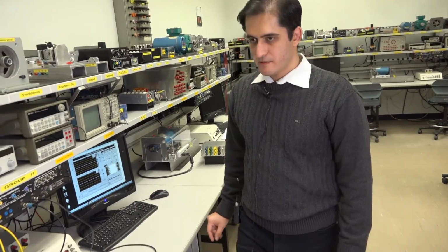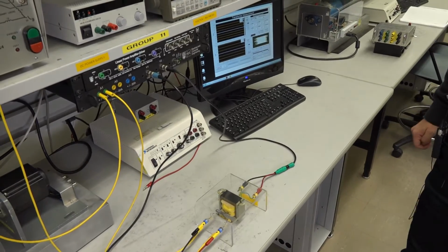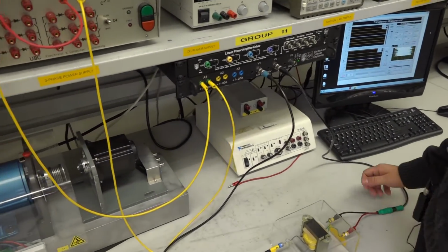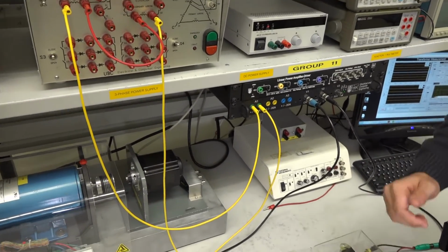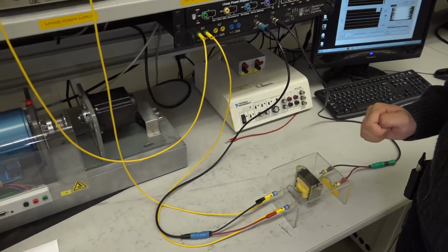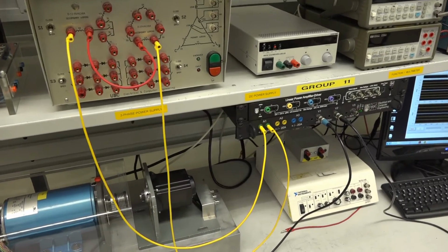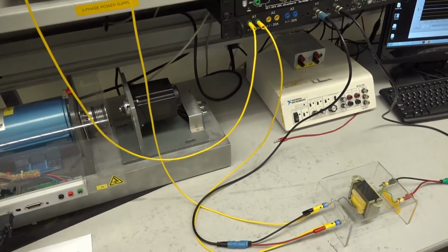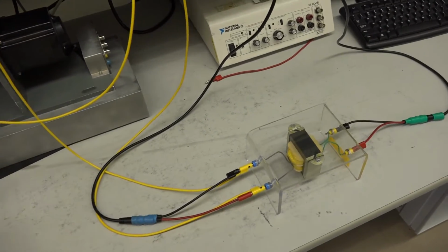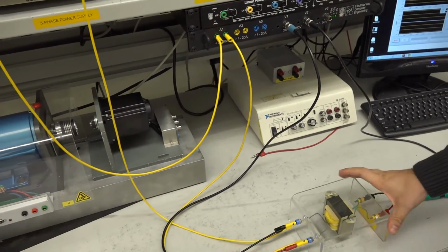The final test that we are going to do here is testing something that happens in AC transformers, which is inrush currents. In AC transformers, when you connect a voltage to your primary side when the transformer is not energized, there will be an inrush current, a current with a very high peak going through the transformer windings, and it depends on at which point in time we're connecting the voltage to the transformer.